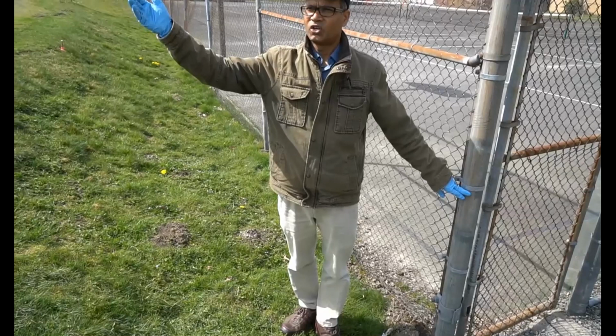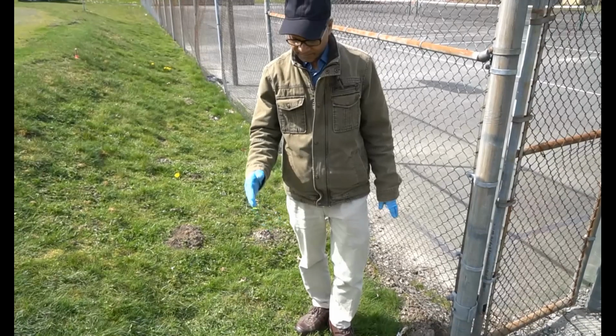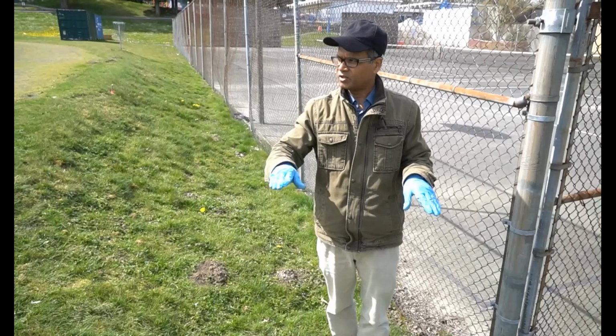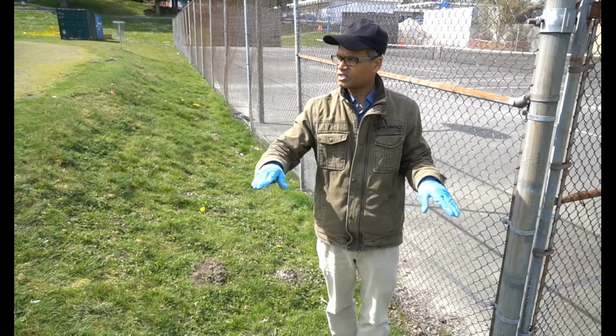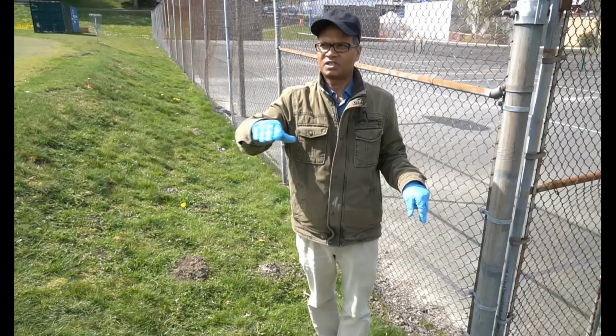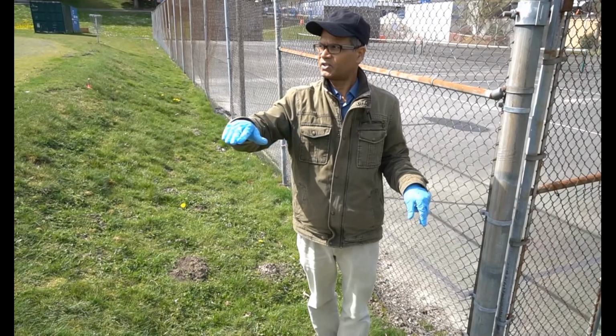That resistance will represent the ground resistance. The resistance will be different at different points, but somewhere the resistance will be almost the same, in two or three readings. So if you draw a curve of the resistance with respect to the distance, we'll see the curve flatten at some point, like a plateau, and that value of resistance is representative of the ground resistance of this grounding system.